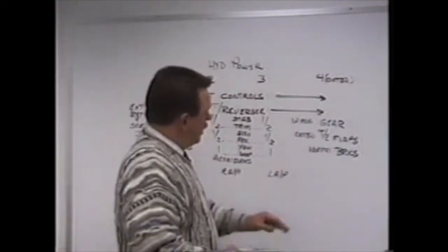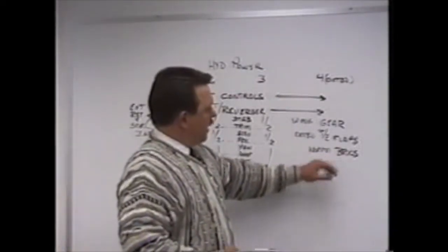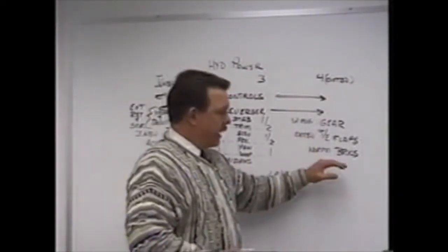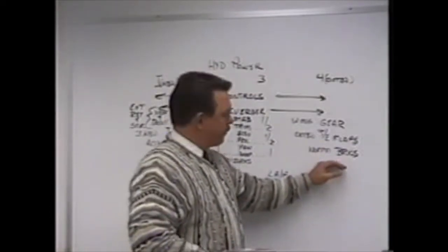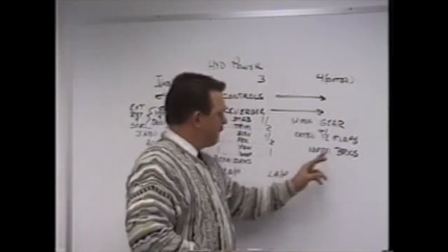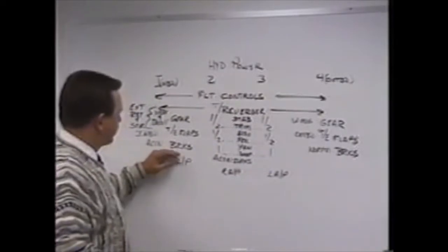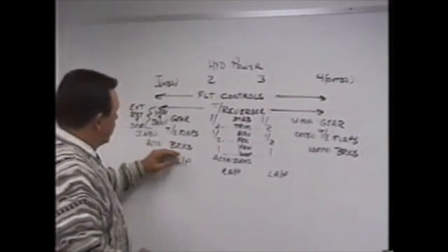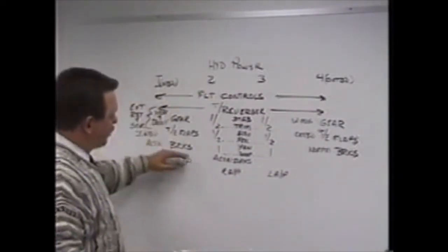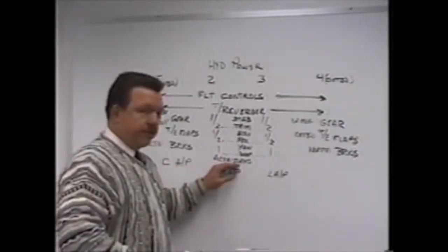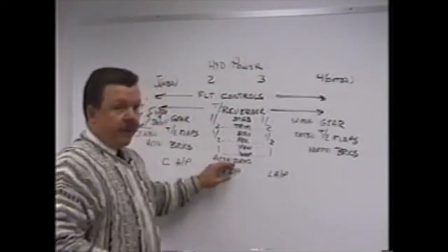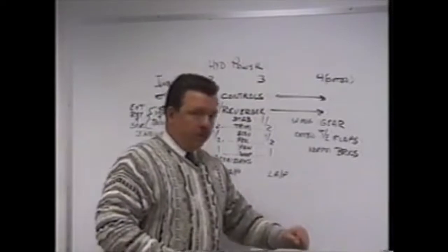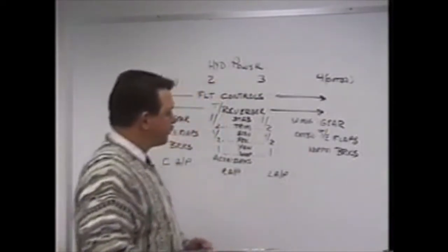All right, let's discuss the brake systems. Normal brakes are on System 4. Everything being normal, System 4 pressurized, brakes are available on System 4. If System 4 was to fail, the brake system would automatically move over to the alternate brakes on System 1. If System 1 was to fail, the brakes would automatically move over to alternate brakes on System 2. If that fails, the brakes will then move back to the accumulator in normal System 4.